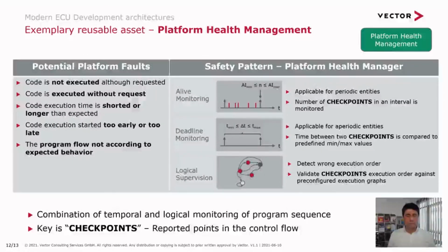And if we compare, or validate, the logical sequence of those checkpoints with the predefined execution graph, we can identify or ensure logical supervision for the software.